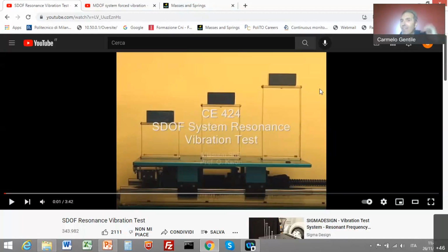So the higher the height, which is in the denominator, the lower the stiffness. Okay, the lower the height, the higher the stiffness. So what I expect is that this system is more deformable than this one, that is in turn more deformable than the first one. So the lower one is the stiffer, the upper one is the more deformable.